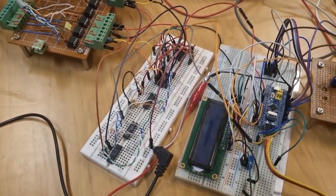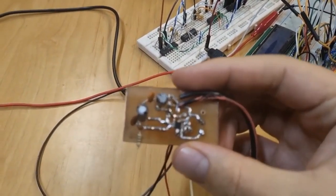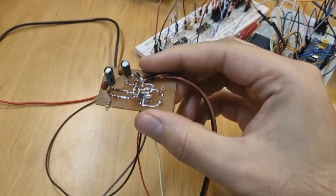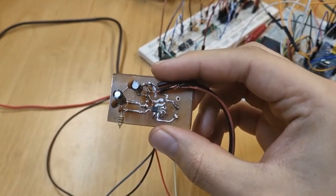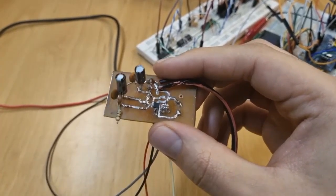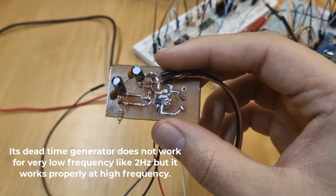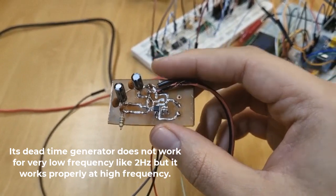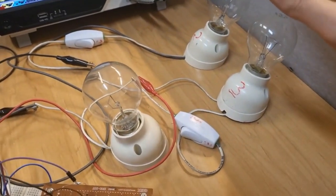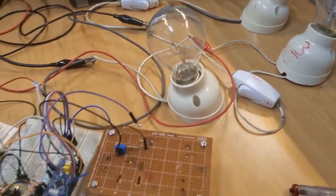Before designing this circuit, I decided to use LM5106. It's a very small IC, as you can see now. It's a half-bridge gate driver, but when I implemented it, I realized that I cannot use it for low frequencies such as 2 Hz, 4 Hz, 6 Hz, 8 Hz, and 10 Hz, because I want to see these lamps blinking. Because of that, I decided to use these frequencies such as 2, 4, 6, 8, and 10.